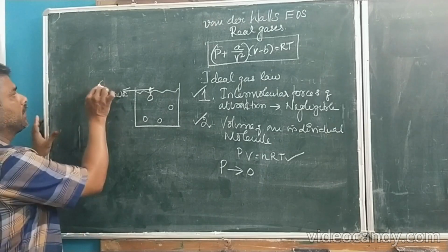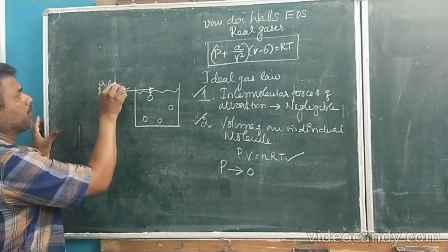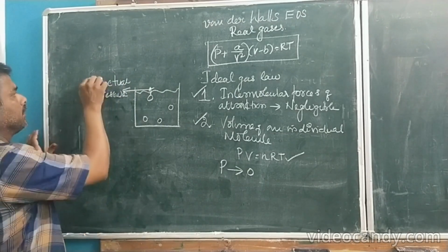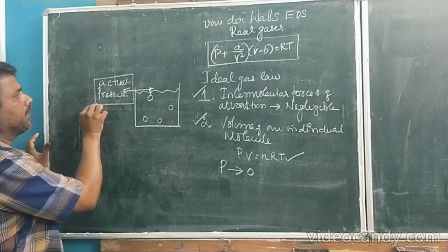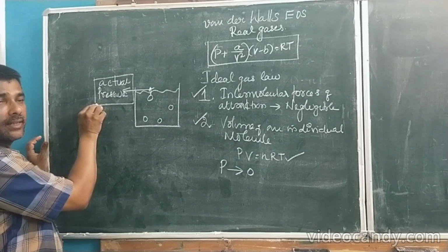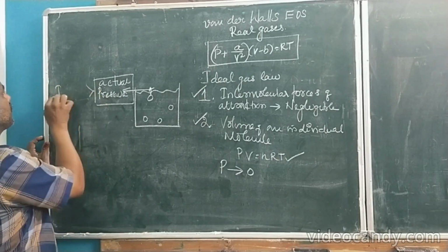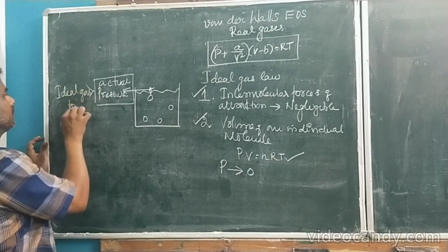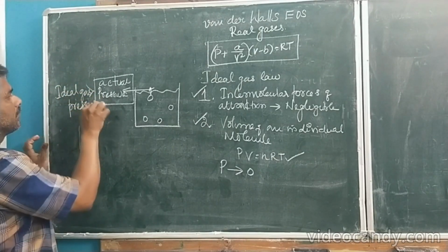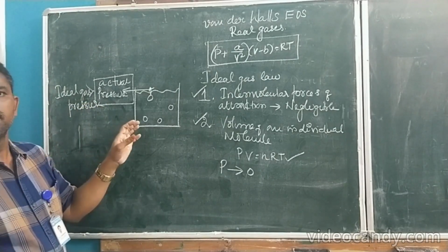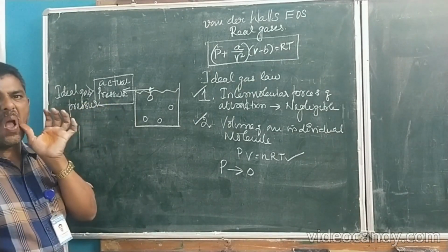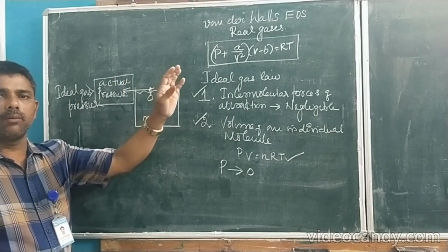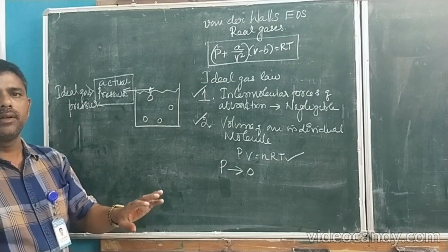This pressure is the actual pressure, and it is always less than the ideal gas pressure. This shortfall in pressure causes a serious error in estimating the molar volume of saturated vapor and saturated liquid.